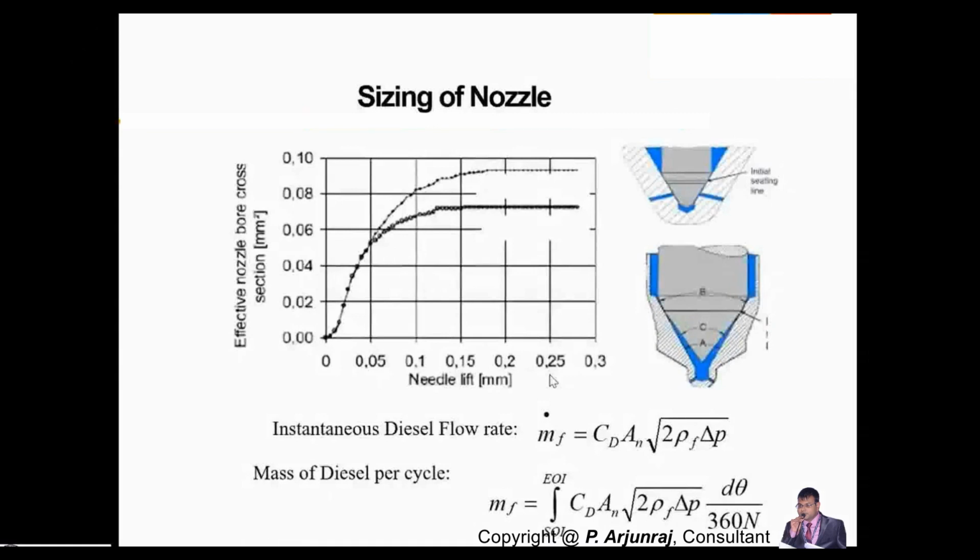Accordingly, this nozzle configuration or the injector configuration will be the same irrespective of the system you're going to have. It can be for diesel, or for gasoline, or for hydrogen, or for alternative or other fuels also. Whatever fuel you're using, you need to put that density value here, along with the pressure drop you're going to get before and after. Considering this, you need to integrate, and N stands for the speed of the nozzle. Accordingly, you get the mass flow rate of the fuel.